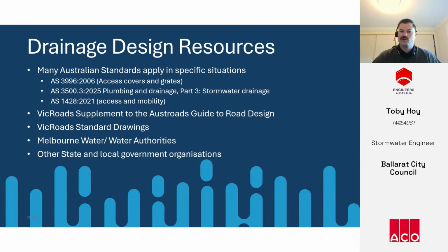Typically, companies sell off-the-shelf products with designs to meet various Australian standards. For example, precast concrete suppliers will make pits to a standard, such as IDM, and provide Class B and Class D lids designed to meet Australian Standard 3996 for access covers and grates, previously mentioned. Australian standards cost money to use for commercial purposes and have only recently become free to view for non-commercial purposes.